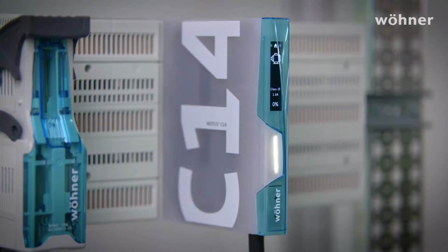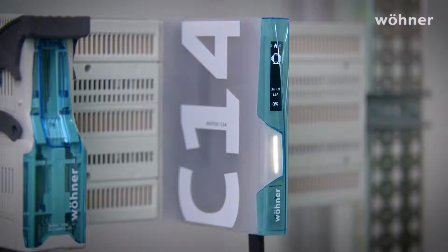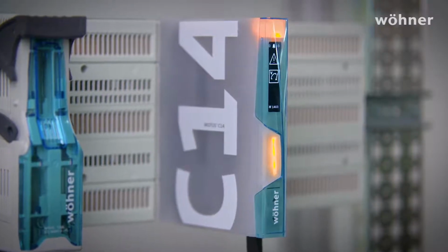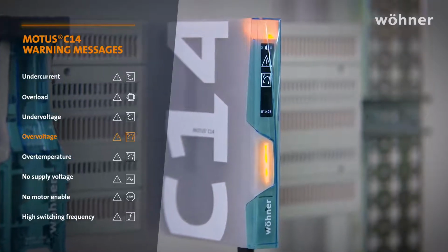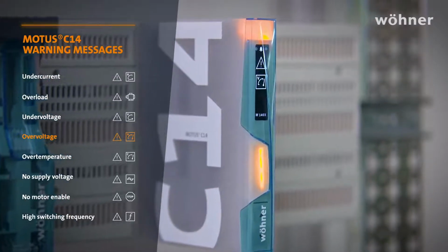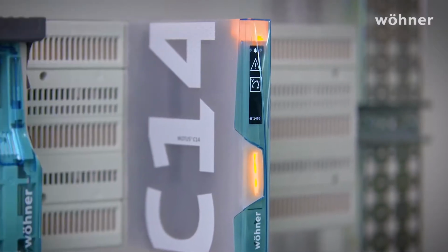The device monitors its peripherals all the time and gives us various warnings or fault signals if it detects something. Warnings are purely informative. Faults lead to the device switching off. For example, let's suppose that your power supply has failed. The main LED is yellow. This is a visual indication of the warning status, and you can see that the casing is also illuminated. In this case, there's an overvoltage affecting the control plug. That's why it's lighting up at the top of the case.